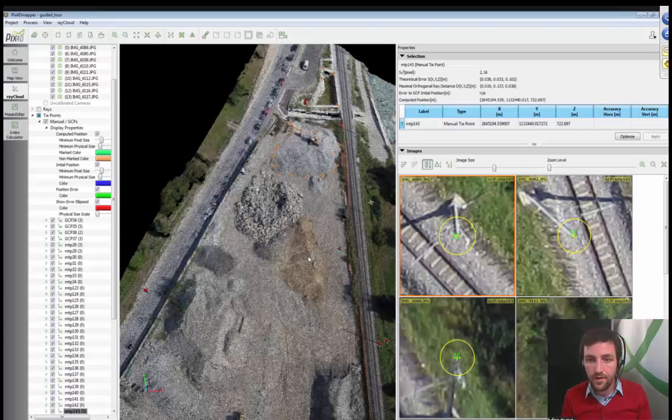Now, these 3 pixels don't have a dimension, so I cannot tell you that's going to be 15 centimeters. However, if you have ground control points of a high enough quality, then the geolocation will be perfect, and then the accuracy of your project will be really 3 pixels. If your ground sampling distance was 5 centimeters, the standard deviation of your accuracy is very likely to be better than 3 pixels, meaning 15 centimeters.